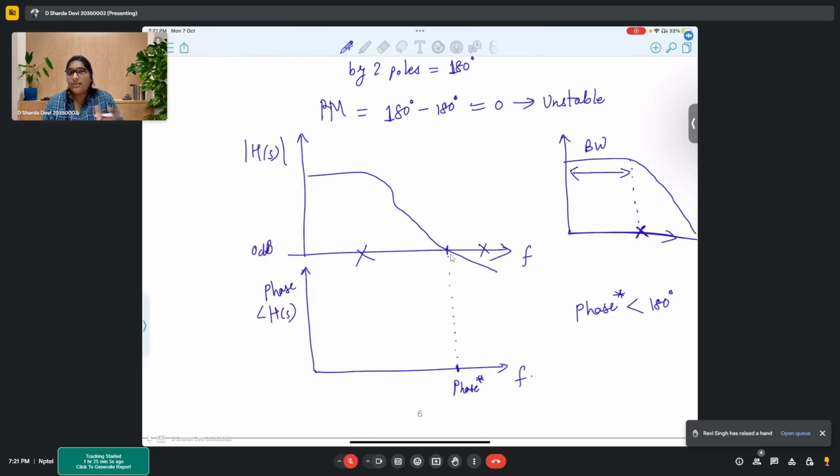So that can also be related to the bandwidth. Here, the bandwidth I mean is the operating frequency range. I'm not concerned about the reliable output, rather whether the system can survive or not. So I'm talking about that bandwidth. The more the poles, the frequency range until which it will be stable starts reducing. So the higher the number of poles, the frequency range for which the system works as a stable system will reduce.